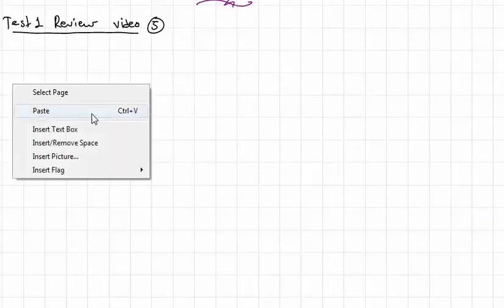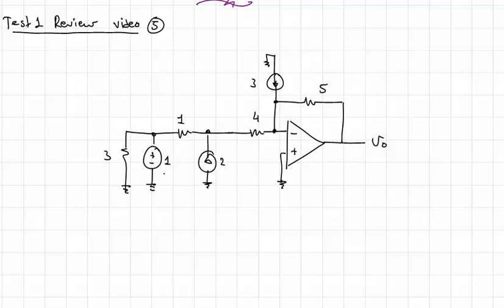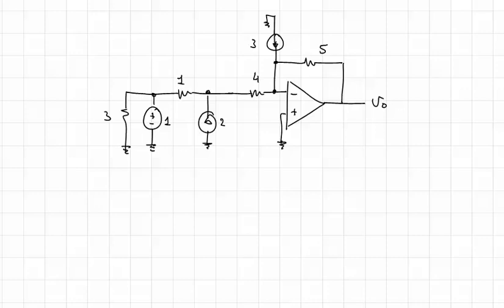So let's look at the same circuit that we've been working with, and let's ask the question: if I said, what is the impedance that is seen when looking into this circuit? What is the impedance seen when looking into the circuit? Your response should be, well, looking in from where? Okay, because there are three sources here, and the impedance looking in from any one of those could be different. Let's consider the three cases. Perhaps I'd give you a problem that would just have one source on it. But it could be the 1 volt there, it could be the 2 amp source, or it could be the 3 amp source. So we'll look at the input resistance for each of those.